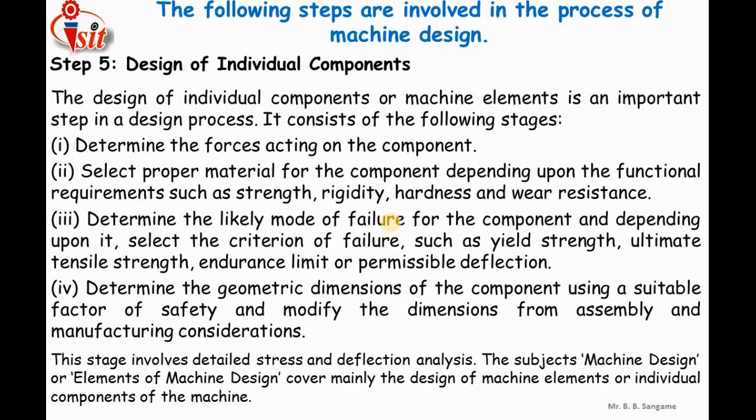Again, what kind of load is there, whether the load is static, dynamic, or impact type. According to the load and the working condition, whether the component belongs to a simple automobile or to an aeroplane, in the case of an aeroplane we have to consider a higher factor of safety. Obviously we need a higher factor of safety in the case of a car also.